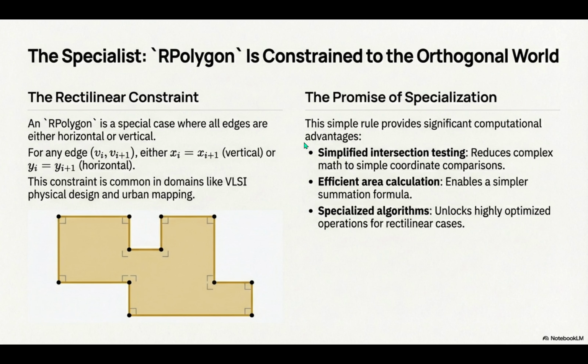It's all grids. We saw in the sources this interesting architectural divergence. It wasn't just about the angles. The general polygon handles generic data types, right? Often floating point coordinates, decimals. But the specialized R polygon almost exclusively uses constrained integer coordinates. Why does that specific detail matter so much? Oh, it's a massive performance and reliability advantage.